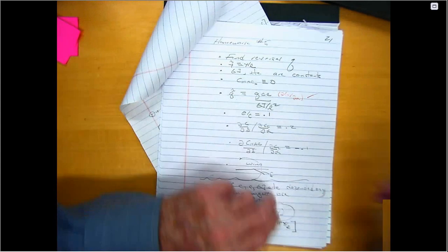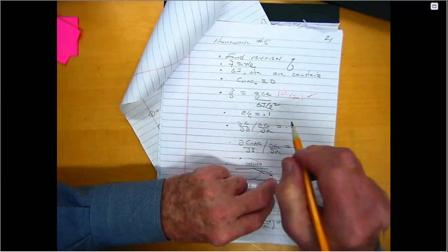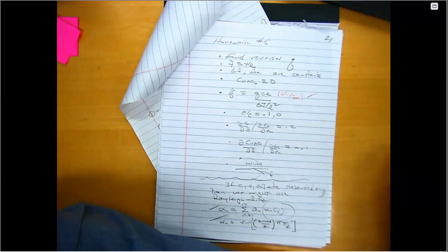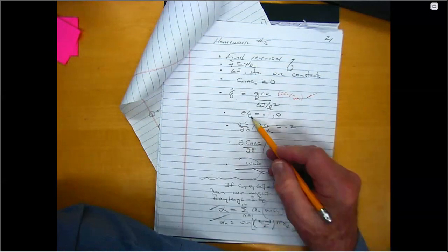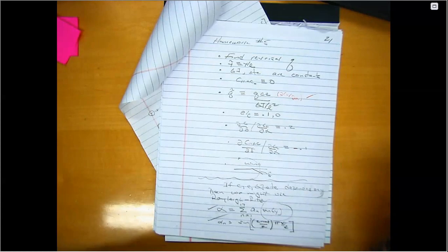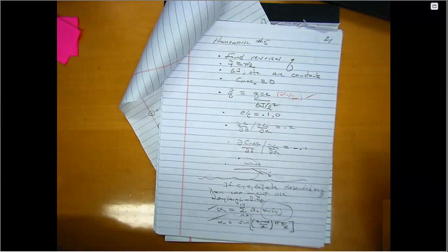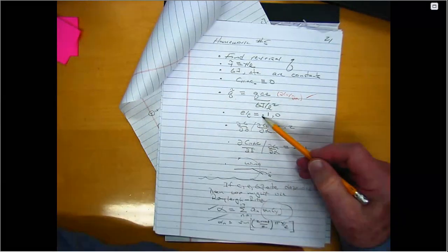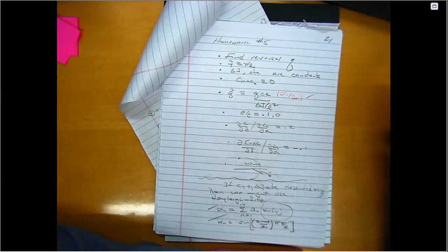So, just for fun, why don't you do two values? And by the way, if you want divergence Q to be less than reversal Q, what would I pick this to be? I pick it to be a big number. Right? Like 1. That would be a big number. In fact, that would put the aerodynamic center and the elastic axis off the plane. That's probably not realistic. But just mathematically, if I want the divergence Q to go down, I would make these bigger and bigger.